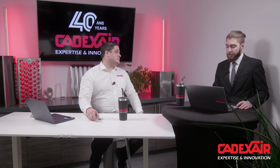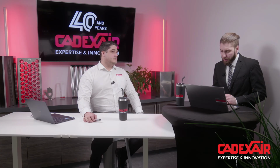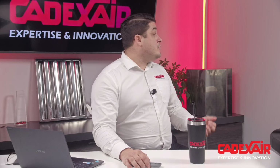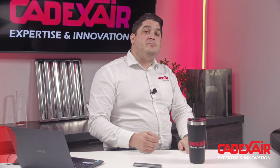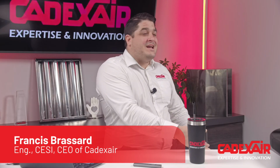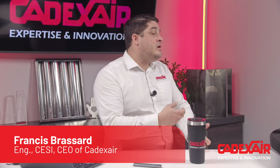So first question I have for you, Monsieur Brassard. Do we need fire protection in the commercial hood for a hot plate? You mean the induction plate? Induction plate, hot plate, yeah, they're technically synonymous. If it's under the hood, yes, because you can put a pan and cook a steak in it. So technically, if it's under the hood, you need to do it.